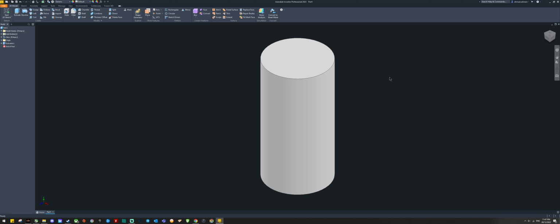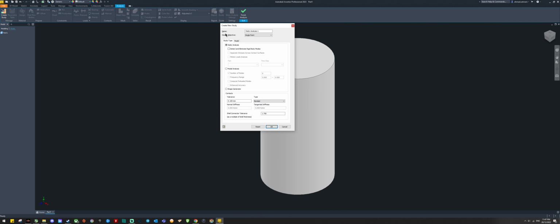There are many types of stress that can be applied on top of this component. One is tensile, and the second one is compression. So I'm going to do compression, where the component will be pressed from top. So from Autodesk Inventor Professional, select stress analysis and select create study, and this one just keep it as it is for static analysis and select OK.